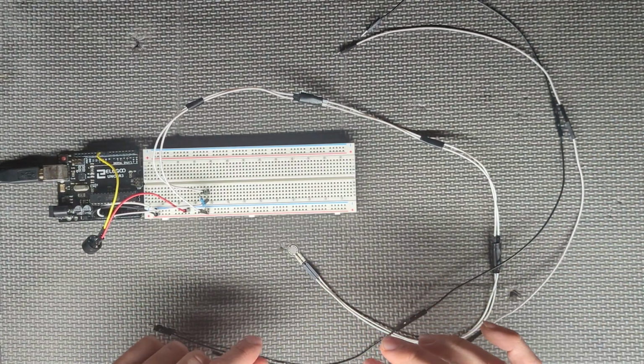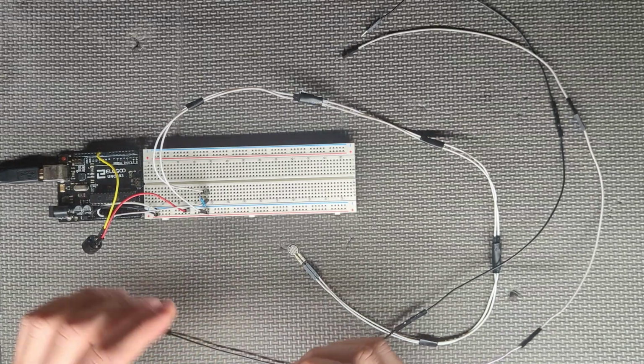We are now almost ready to start writing the code for this, but first we need a way to detect when the lid of the toilet is actually lifted. My first idea was to find out what values the force-sensing resistor read when the lid was down and the seat was down versus when the lid was up and the seat was down, but the FSR ended up not being sensitive enough to reliably tell the difference. Instead, I've opted to create a physical switch that closes when the lid is up.